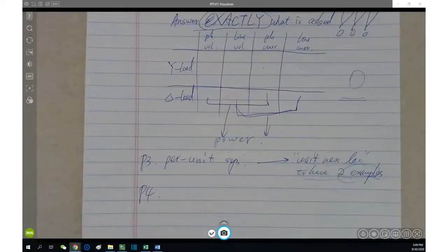Excellent. I received the correct answer from Anil. It's about the transformer. In the power system, different voltage level networks are connected, hooked up through what? Transformers, right? So the primary end is one system, the secondary end is another system. You have the same quantity, the same actual value of current or whatever it is. On the primary side it is 1 per unit, on the secondary side it becomes 0.5 per unit. That's why we need to learn how to transfer this.